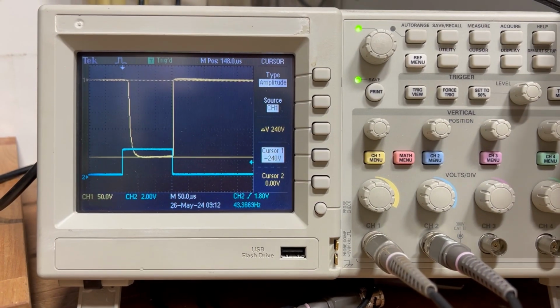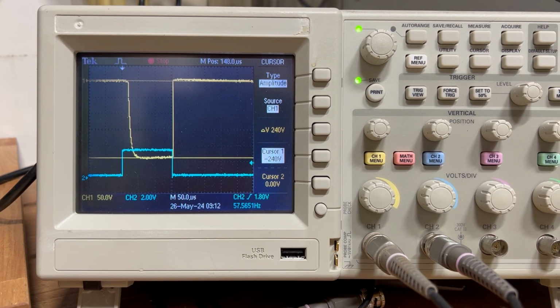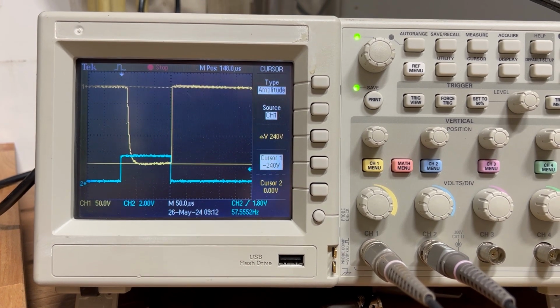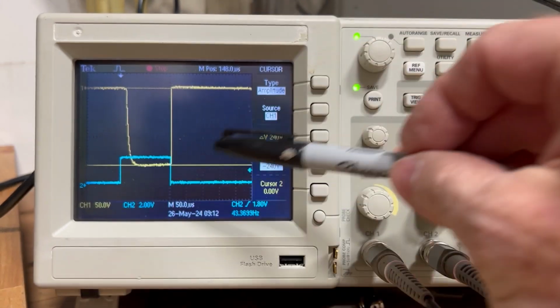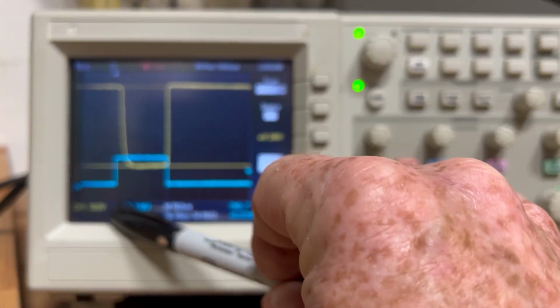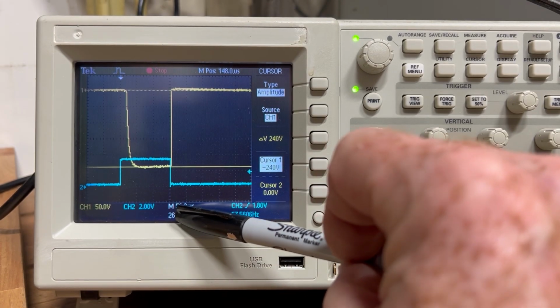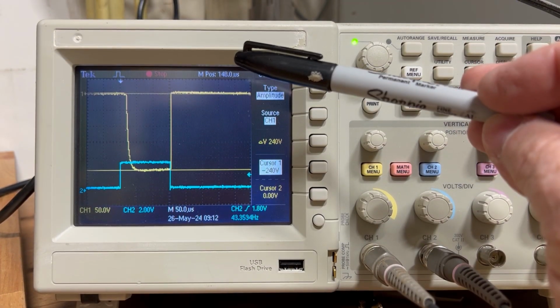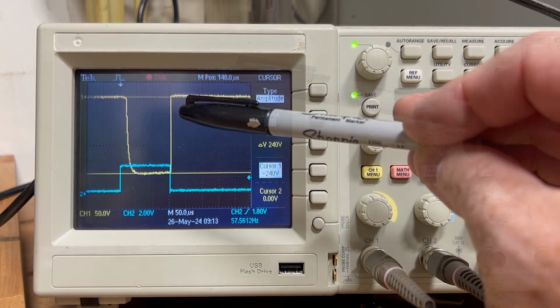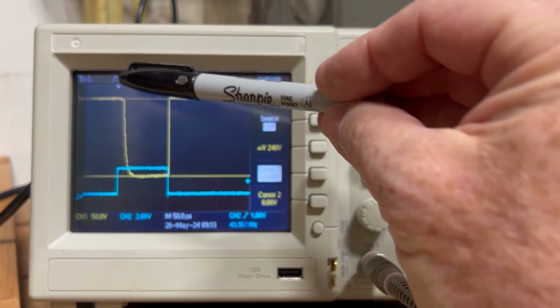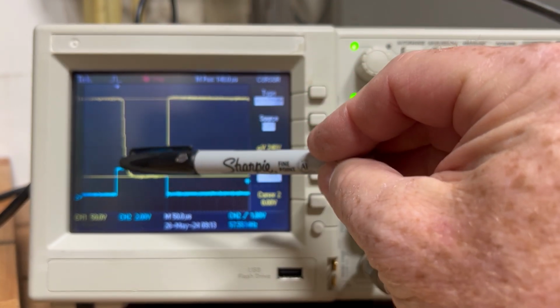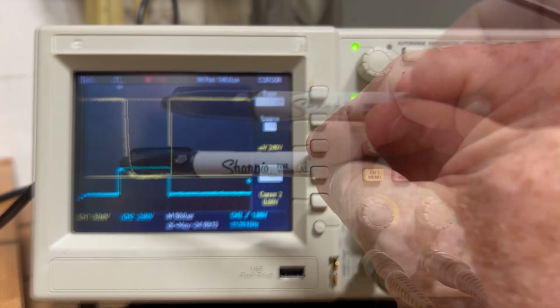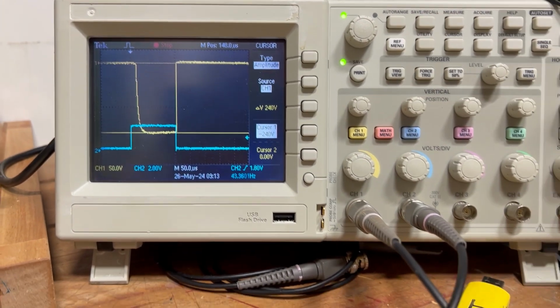So we see here on channel 2, this is our digital input from the decoder. It's a nice square pulse. Looks like I'm going for about 150 microseconds on this. The yellow curve is the voltage to the selector bar. I just picked a selector bar at random, but you can kind of see a little RC charging curve here at the front end of this thing, and that's kind of to be expected.